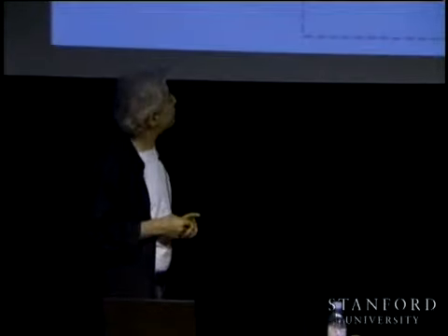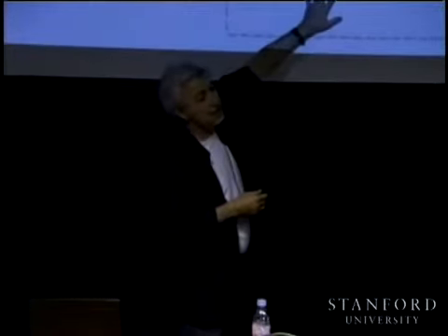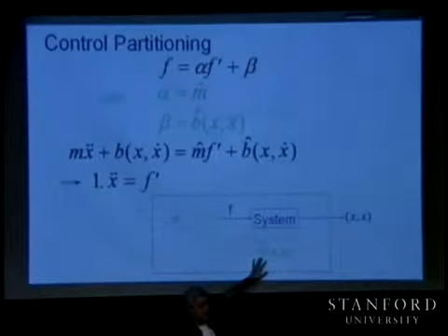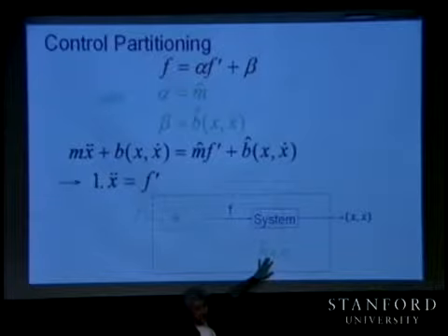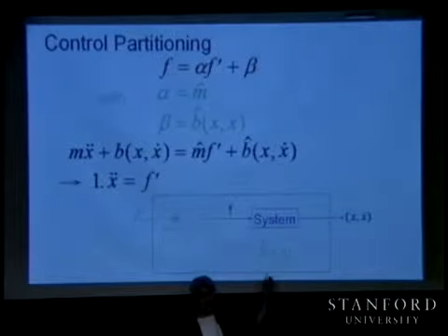So in fact, with many degrees of freedom, we will be able to do the same thing, where this becomes the mass matrix, and here we will have V and G. You remember V? Centrifugal Coriolis, and G, gravity, and you can add the friction as well. Okay? So essentially we are designing a non-linear controller to compensate for centrifugal Coriolis, gravity, and to decouple the system, to decouple the masses, the inertial forces, and to achieve a unit mass system behavior.